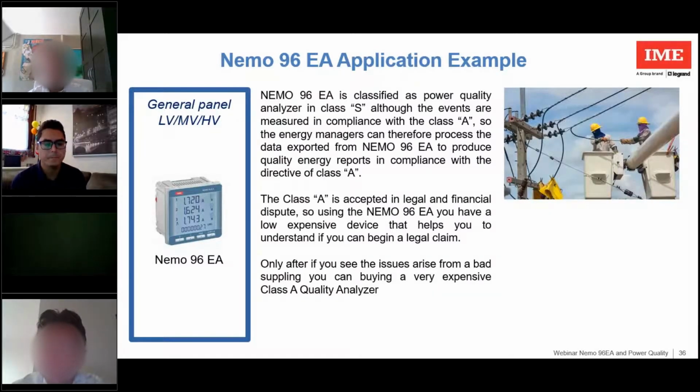So, what does it mean by the possibility to set a total harmonic distortion threshold? Can you repeat? Sorry, Matteo. I think it means if there are some possibilities to set a total harmonic distortion threshold. A threshold? No, this is not one of the parameters, because the THD is a value to maintain under control in real time. So it's very difficult to put a threshold on it. More probably, you would put a type B differential relay for this type of events.